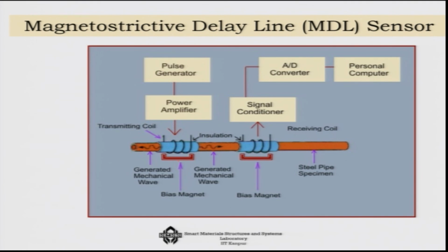Now, the same signal that you give here, you can get back here in no time, because the electromagnetic wave is transported instantly, but the actual mechanical vibration signal gets a delay. If you plot time versus current, one signal is the electromagnetic excitation, and if you get the pickup coil current, you will see there is a delay in the system.